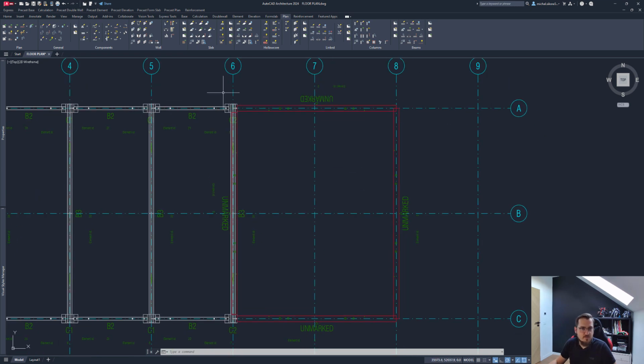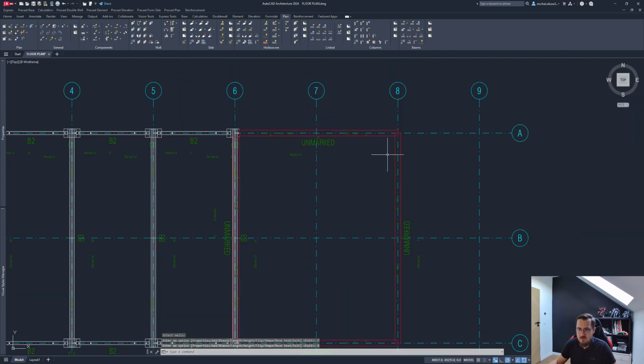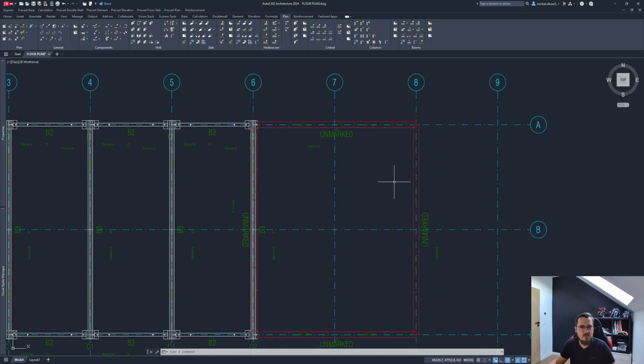One thing that I'll do, which will be slightly easier for us, if it bothers you in any way, you can edit this wall and just say flip, which will basically turn the text around for you to change the orientation, so everything is nice and clean on the drawing. Right, so let's continue, and with that what I'll do now is I'll split those walls.